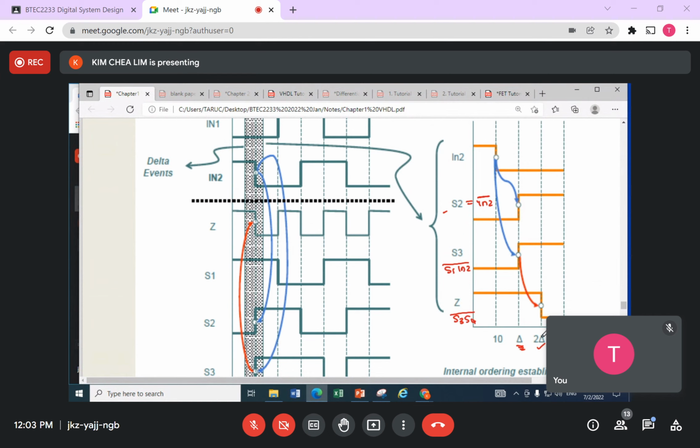But here is trying to tell you about the simulator itself. When you make the timing very small, you actually find that they need some time to react. It's not exactly at the same time. A little bit of delay changes. So therefore, when you are doing any simulation, if this is the input, don't ever try to see your output exactly at the same time where this is changing. Always take a little bit of delay. I want to see the output at different timing.